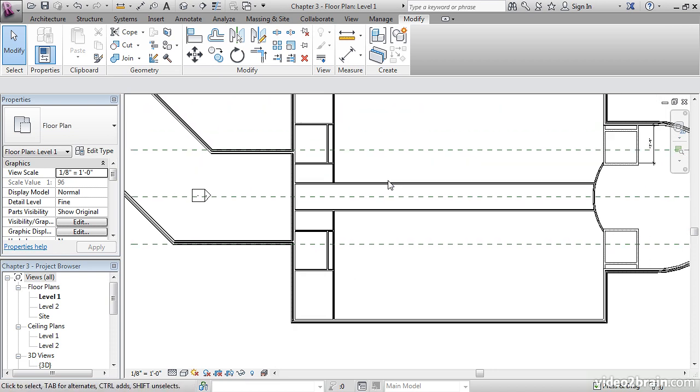Yeah, I had you model a lot of walls, but I can't stress enough the importance of having this procedure down pat. But did you notice any similarities between the different commands? Learning how to place interior walls is exactly the same as exterior walls and is exactly the same as a lot of the other procedures you're going to see in Revit.